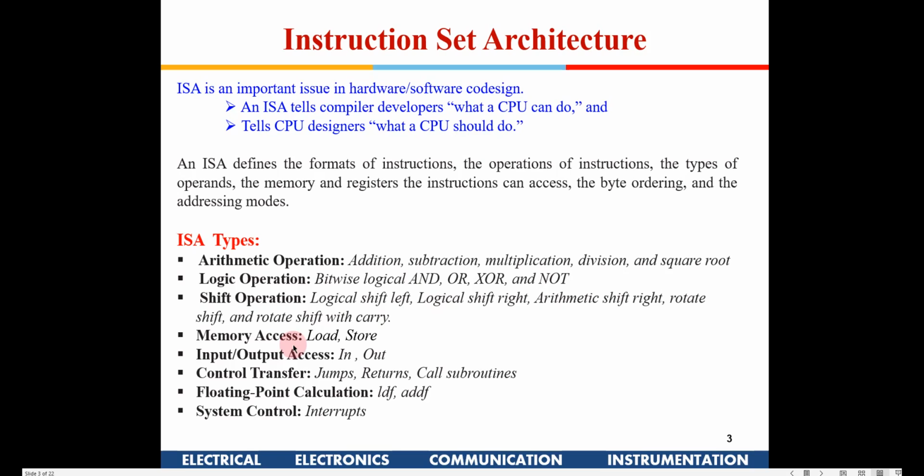And then memory access. If you have to fetch some data from the memory into some register, you can say load. Load means it is loading the register from the memory. Store means you are storing some data into the memory from the register. So these two commands are used for loading data from memory into the internal register of the CPU, and for storing the data from the internal register of the CPU to the memory.